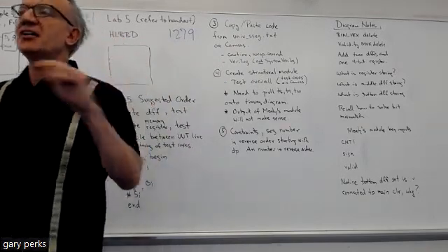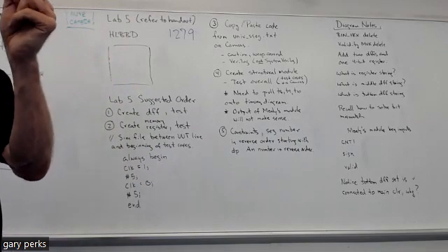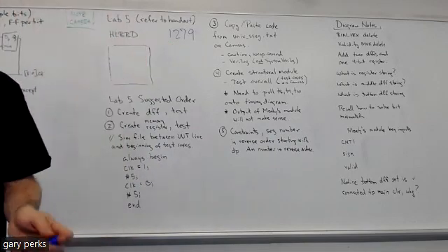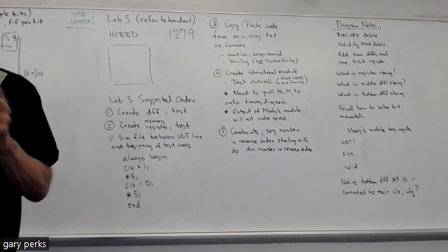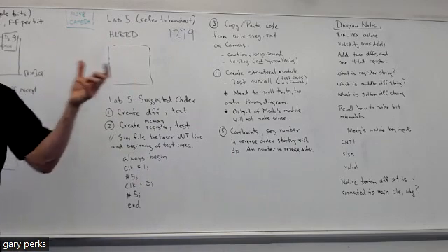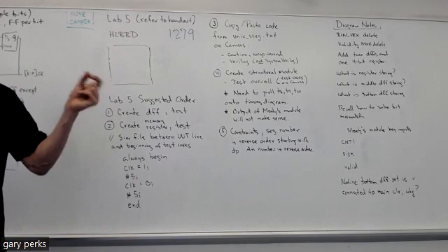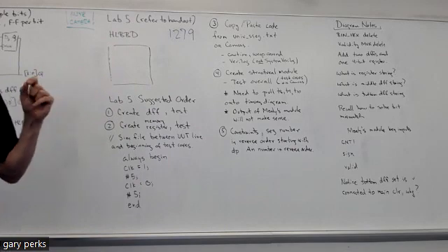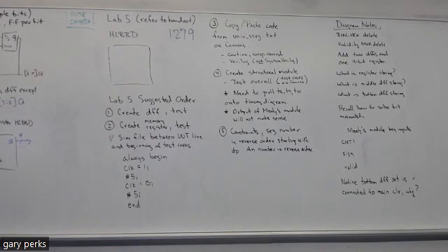If you choose System Verilog and you put that Verilog code into that System Verilog file, you're going to get all kinds of errors. You're going to see red lines everywhere. Okay, because Verilog does not use logic like we do in System Verilog. You know how we use logic to declare internal signals? In Verilog, they use the word wire. And then logic here, when we have an output within an always block, like we do in System Verilog, in Verilog, they use reg, R-E-G. Okay, and then there's some other differences, like in Verilog, you don't have an always FF block, it's just always, and you don't have an always comb, it's just always.